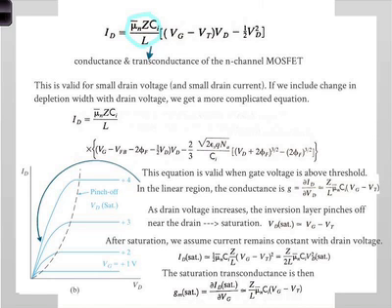But you can see, in principle, you can get very high transconductance. In order to get high transconductance, what do you need to do? Look at those terms there. Actually, it's a good question. Take 30 seconds, look at that equation. Let's say I want very high amplification. What do I need to do? Think about that, because that's one of the requirements. You want to build an amplifier, you want to design a device which gives you lots of amplification.